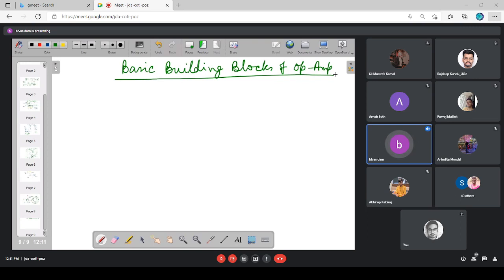Now, what is one operational amplifier? This is nothing but one basic difference amplifier, or a special type of difference amplifier. So using the operational amplifier, we must be able to realize the function of one difference amplifier. So the very first stage of the operational amplifier should be one difference amplifier, where two inputs will be there and one output will be there.